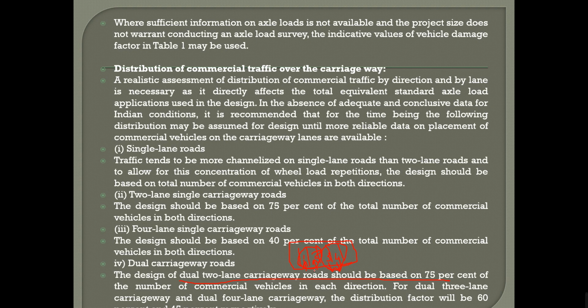those vehicles are going to get shifted from lane 1 to lane 2, lane 2 to lane 1. Do you understand? Hence the localization of the loads or wheel load axle configurations is not going to be focused on one particular point. It is going to get distributed in the lateral direction. Hence, the percentage of vehicles that are considered will be lesser.